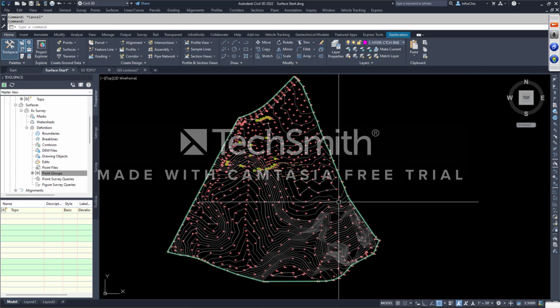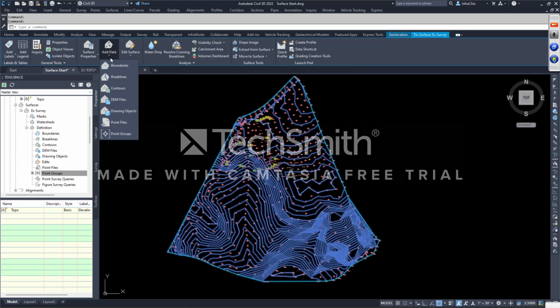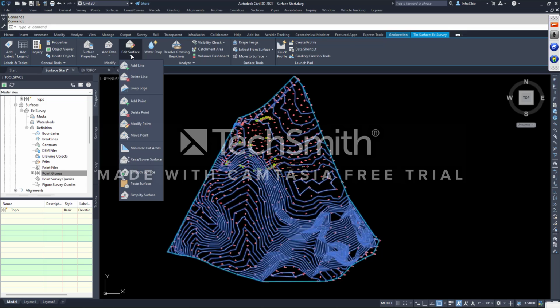If I select any contour line in the surface, it lights up. It's a surface object. And when it lights up, I get the new ribbon. You will see that you can add data. Everything that you see over there in the prospector is now available up in the ribbon. Edit surface, which we didn't look at much in the prospector, but it's the identical commands.